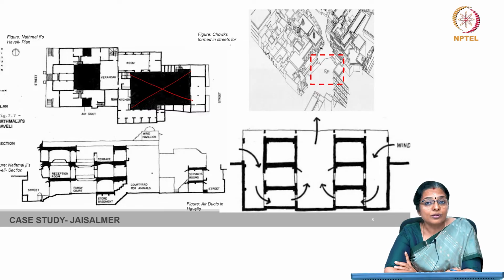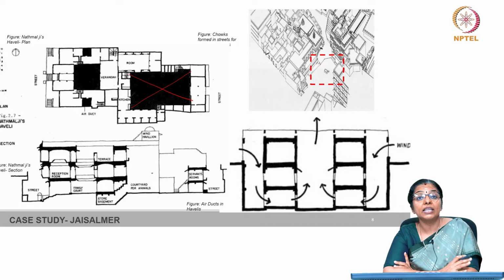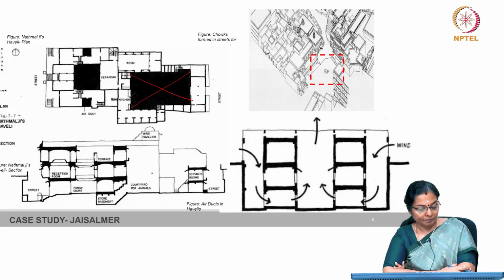The stone walls also have a large thermal inertia. So, the high thermal inertia of the massive stone walls coupled with the wind deflecting shafts effectively temper the air before it reaches the living space. This process bears similarity to the cooling mechanism which is observed in the Iranian wind towers.